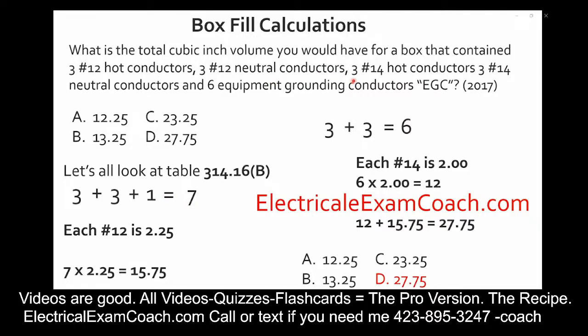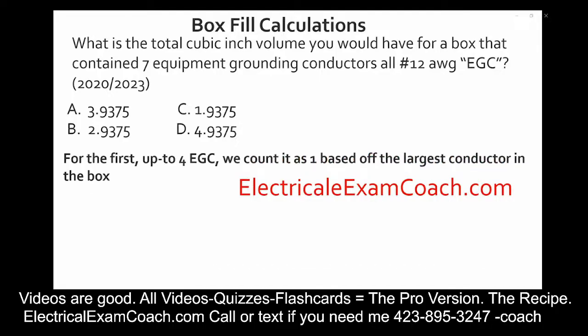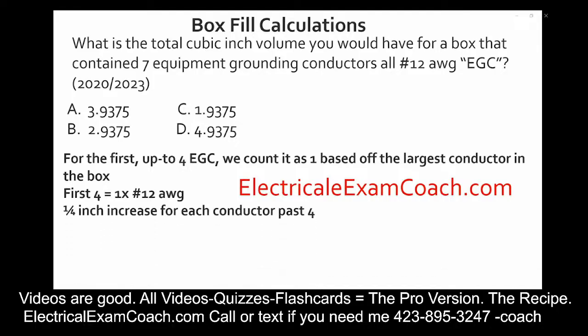Now let's move on to the 2020 and the 2023. What is the total cubic inch volume you would have for a box that contained 7 equipment grounding conductors, all of the 12 gauge persuasion in the 2020 and the 2023? I left out all other conductors because you're going to use the same rules in that after you do this calculation, you group it with whatever the largest conductor is in the box, like you learned previously. What we're going to do is count the first 4 and count it as 1. And then a 1/4 inch increase for each one past 4.